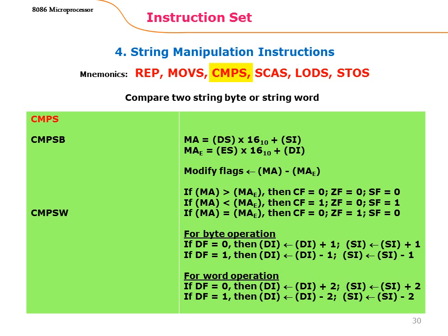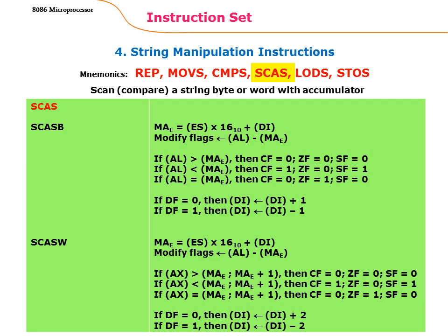Compare string: compare two string bytes or two string words. The content of SI is compared with the content of DI, and whenever we are performing the comparison operation, we can perform it based on the status of the flags.